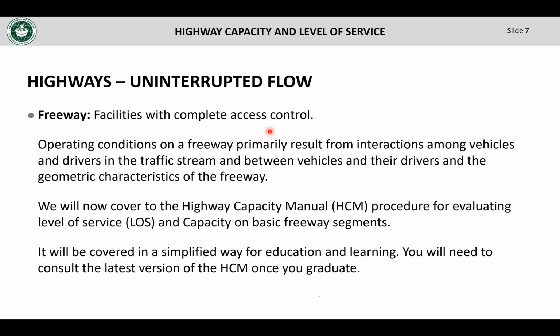There are some sections where you have lateral roads, and those lateral roads have access to businesses. You cannot access the freeway directly from those roads. You have to go and look for the closest on ramp, and the same thing to leave. So access is limited to on ramps and off ramps, and what makes those unique is that you have only merging or diverging maneuvers, right? There's no crossing. There are no cross streets on freeways. So access control is one of the defining characteristics of freeways.